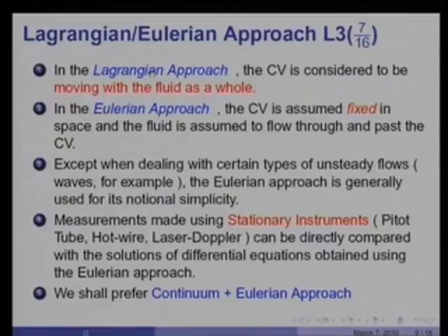When is the Lagrangian approach invoked? It is invoked only in the study of certain types of unsteady flows, such as free surface waves, for example, but this is not something of interest to us, and therefore we shall prefer the Eulerian approach to application of fundamental laws to control volumes. There is also one more advantage when we consider the Eulerian approach. As I said, in the Eulerian approach the fluid element is fixed in space. Although located inside the moving fluid, it is fixed in space.